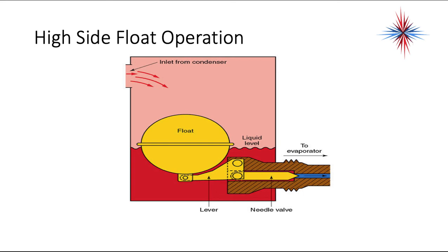For air conditioning, you're going to see cap tubes in window units and small PTAC units. You're going to see fixed orifices in residential split systems, especially the older ones. You'll see the piston type metering devices in heat pumps. You'll see TXVs in just about every type of air conditioning system out there. TXVs right now are the primary choice of manufacturers in high efficiency air conditioning and heat pumps.